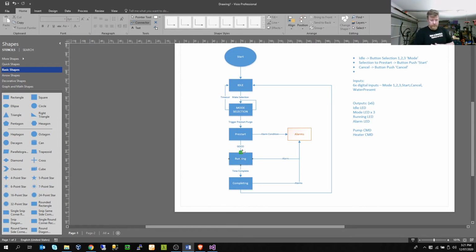So for example, if you've got a 4 to 20 milliamp signal for water level in a tank, I personally wouldn't want to be trying to read 24,762 and mentally calculate how much of 32,768 that is as a percentage to work out how full the tank is. I would suggest it would be better to scale that to 70% and then work in your logic with 70% or 71% or whatever the number is, and then scale that back to your 0 to 32,000 number and work purely in numbers or ranges that make sense to the human.